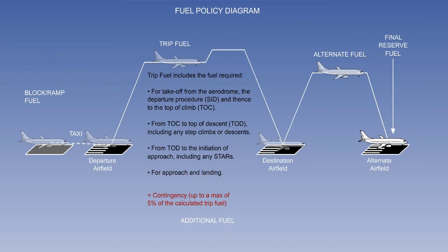There will also be a case for taking additional fuel when the destination aerodrome is so isolated that no alternate is available, and so on this occasion an amount known as island holding is required. The necessary fuel carried to cater for the possibility of these occurrences is called additional fuel.